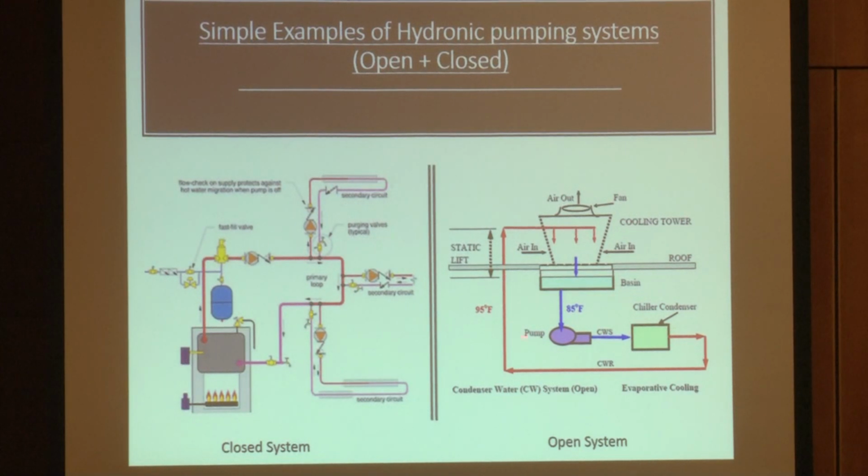We have to be very careful with these open systems, maintaining a certain height between here and here, because when you start varying the heights between the pump and the water levels, that's when you get into trouble with getting air into the system, and also you can cause cavitation of that pump. Very simple to get yourself in trouble in an open system. Much more difficult to get in trouble in a closed system.